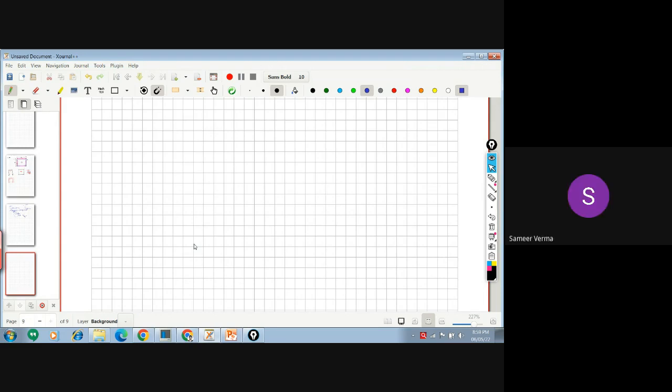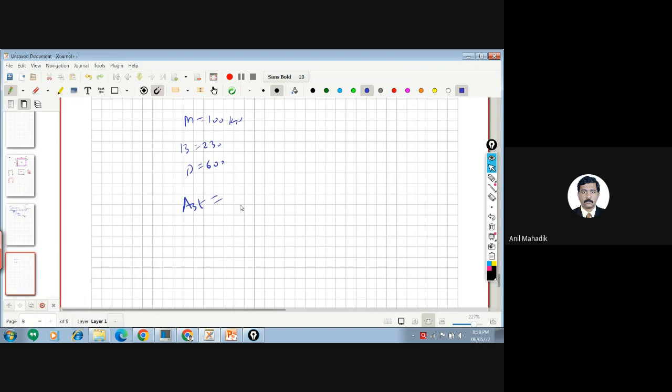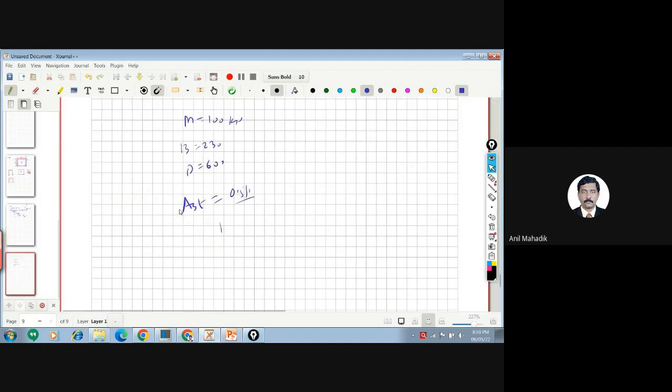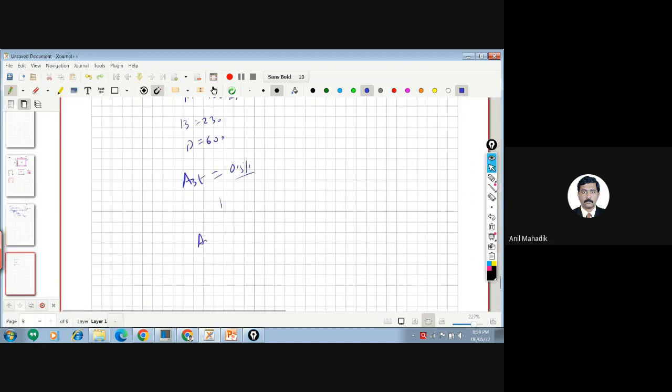Yes, sir. So, it is really easy to teach, let's say, the bending moment is 100 kilonewton-metre, B is equal to 230, D is equal to 600. Then I will use one formula, AST is equal to this, 0.5 fck upon this and that. My formula, then calculate AST minimum, then calculate shear stress.